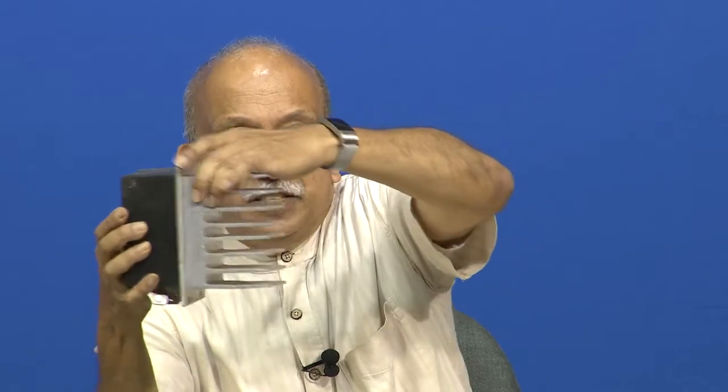Now we end up with the manufacturer, usually two ways they do. They will give you, in fine print, all our things are valid provided this surface is kept at 50 degrees centigrade. Now how do you keep it at 50 degrees centigrade? This is where our problem comes. Obviously, one of the simplest ways is to attach a heat spreader to it and put a fan. Looks good enough, isn't it? Small heat spreader and a fan. Alternatively, if you suspect the fan itself is not enough, I have put this monstrous thing on it, you have seen it, no?